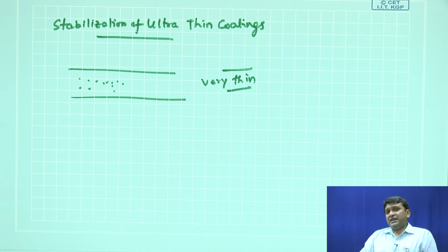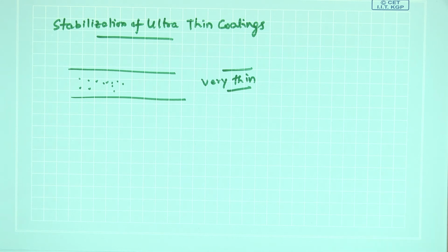Now you understand that you probably have to have a certain minimum thickness of the photoresist layer in order to ensure that the resist layer remains stable. With this type of very advanced research, one can in principle make films which are very thin but also stable, and trust me, this has a huge application.